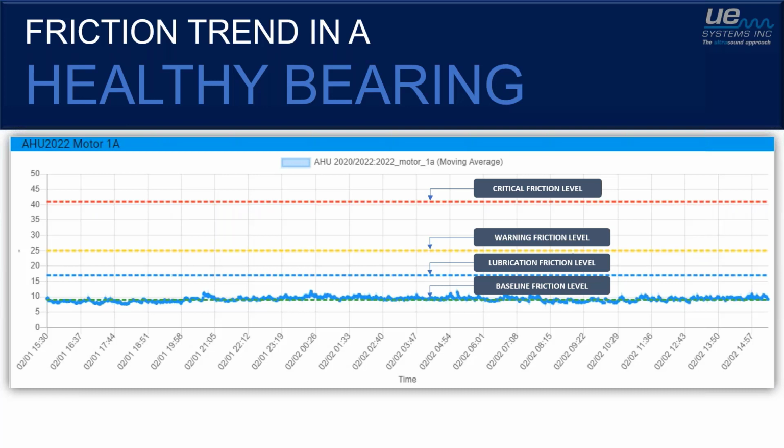Okay, and what you're seeing is typical of a bearing. You're going to have some bumps, some impacting. It's not going to be an absolute 12 decibels and just stay there forever, right? And in fact, this is a variable speed fan, so it's going to go through varying load changes and speed changes as well. And as Mark pointed out, as that speed changes, we'll start to see that fluid friction, and we will see it.